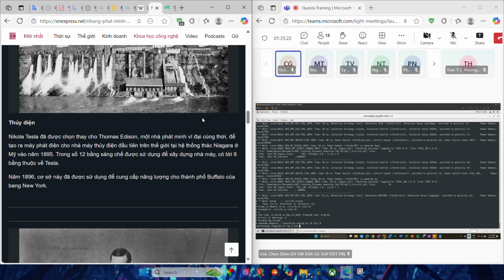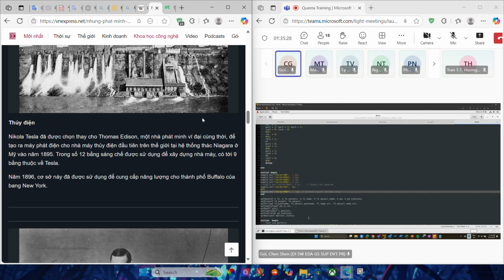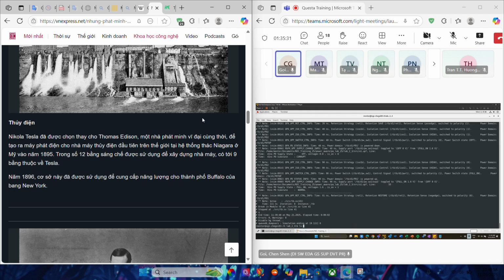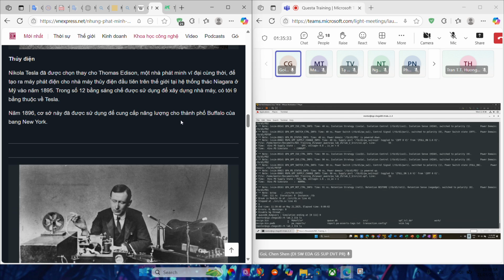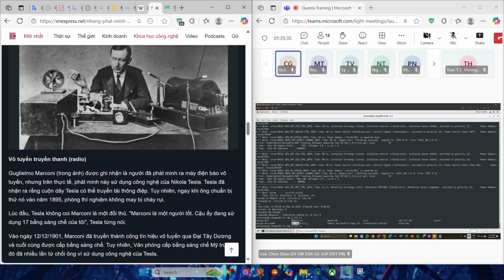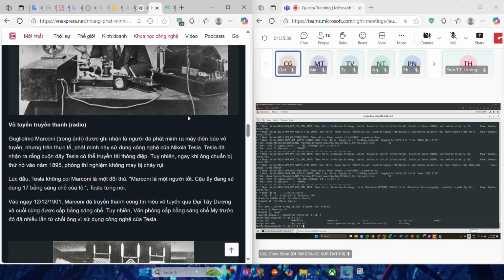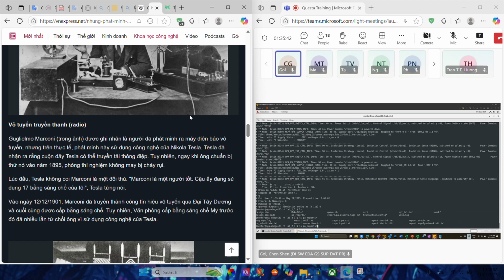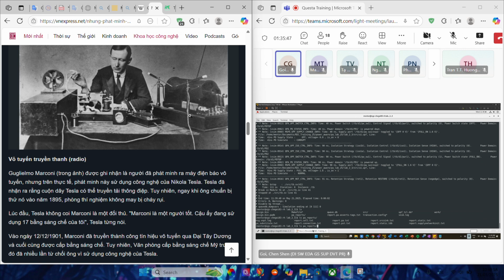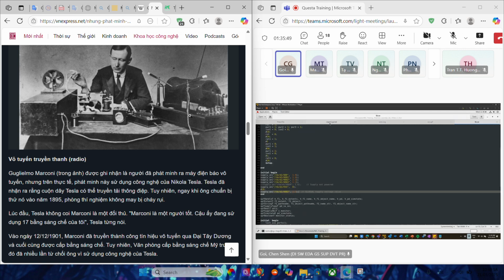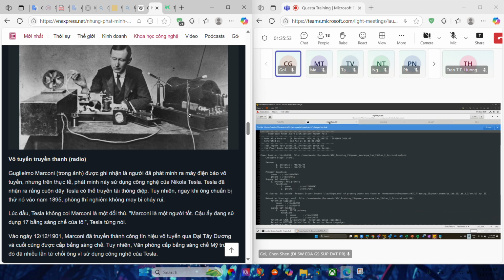So anytime you see an error with power aware, you don't have to worry. You just have to remember where to find the log files and everything. So let me give you a reminder again. If you have a PA generated report, then you will have to check from the reports, PA_reports. Inside PA_reports, the general file that you would like to see is report.pa.txt. And this file, actually, we haven't seen it yet. I haven't shown you, but it's easier to debug from the file itself.